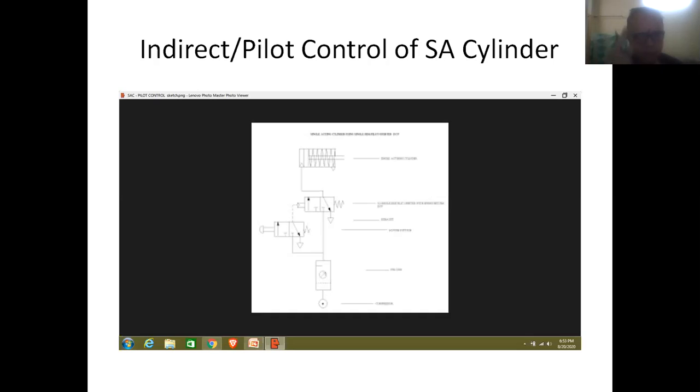So the push button will be moving the plunger in reverse direction, putting the valve in first position. And in the second phase, it will be releasing force on the plunger. Therefore, by virtue of spring action, the element will be moving in forward direction, ultimately coming to second position.